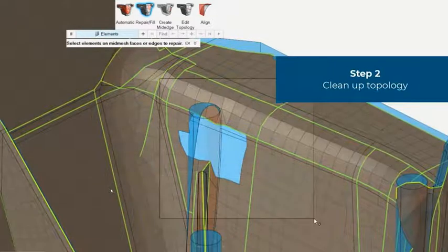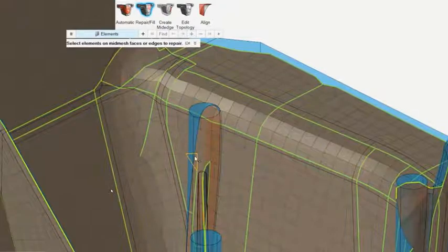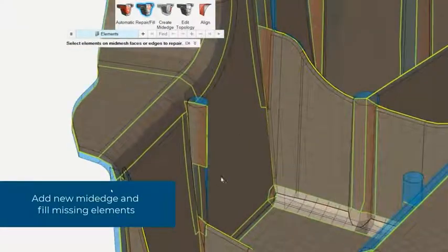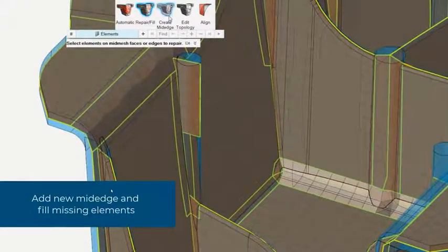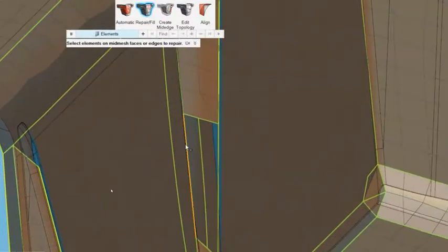From here, these tools operate on the mesh representation of the midplane, not a geometric one. So editing faces, filling in faces, or removing features from geometry onto the underlying mesh will now dictate how the batch mesher handles them when we perform a rebuild in the end. So we're able to create new edges by nodes or derive them from the geometry.